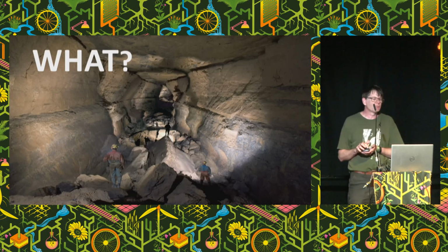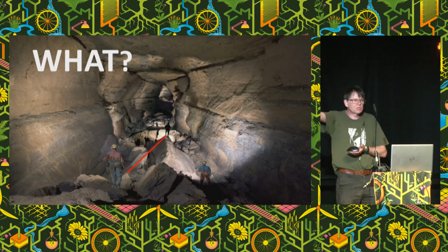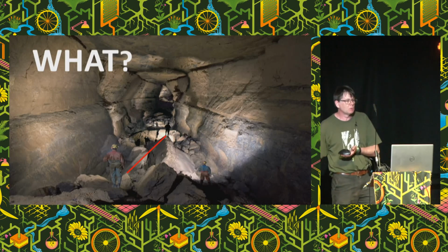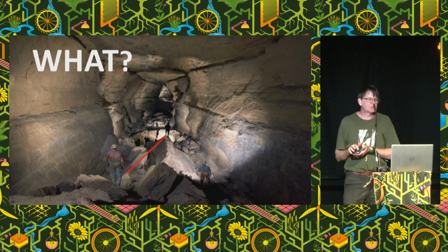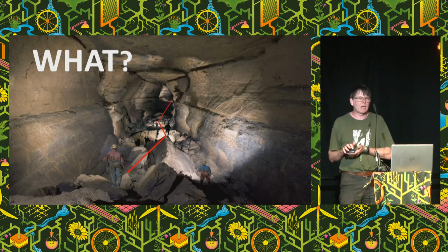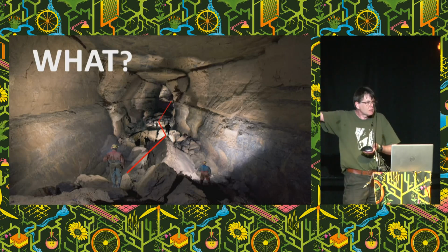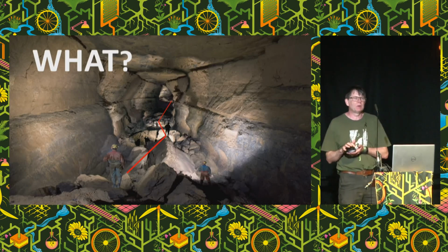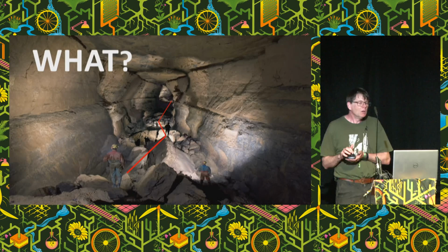So we pick a convenient rock that gives us a good onward sight, and we measure a three-dimensional vector, so distance, compass bearing, and declination, so what the slope is, between those two points. And you just carry on doing that through the cave to get your basic where-does-the-cave-go information. That's the backbone skeleton of a cave survey.